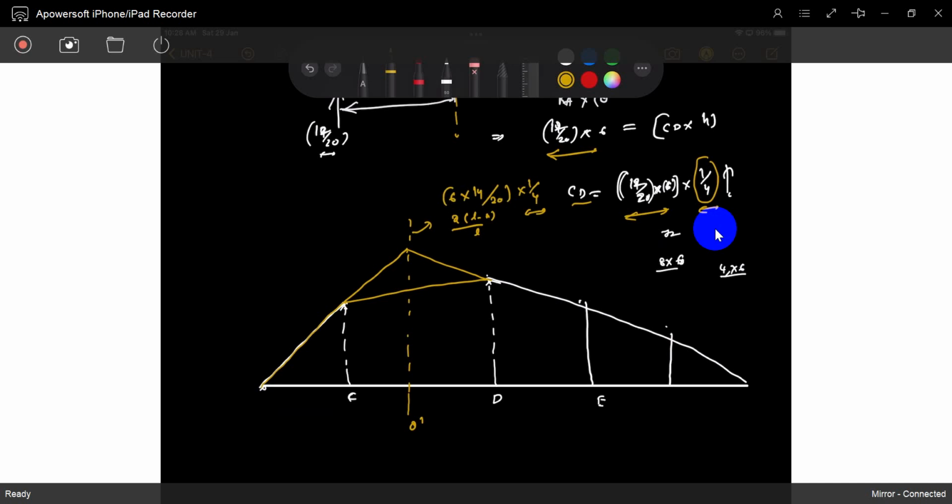You can't miss it. If you write down the diagram directly, later you will join these two values. Sir, why is it joined? Because there is no placing of the loading at the joint of QQ dash. We will get the load at Q only when the load is at D. But the total diagram, we can write down directly, the influence line diagram at the junction of QQ dash, the bending moment influence line. You can write down and join the C and D values like this, because there is no joint in between.